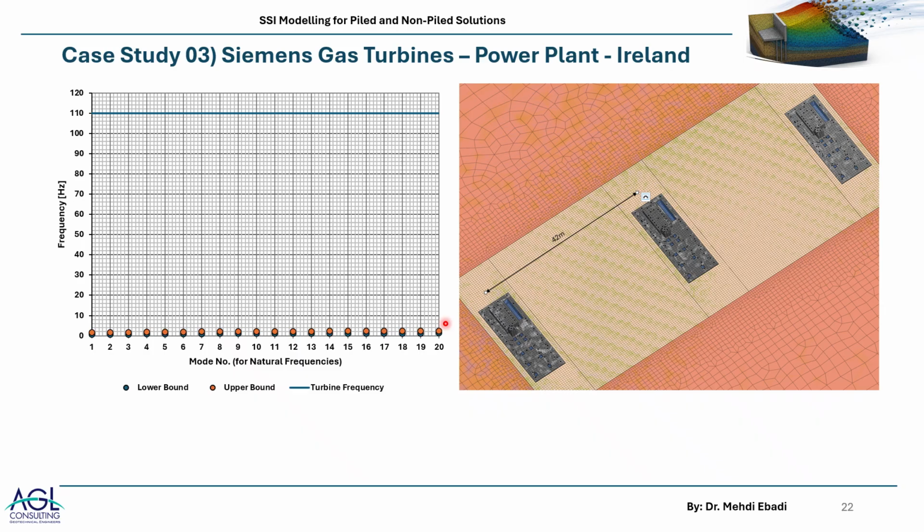Note that although for such a case we have the option in MIDAS to apply a sinusoidal load and do time history analysis, we didn't find such an analysis useful for the needs of the project, because when you know that the settlements are well within the capacity, your system is not at risk of resonance or such, then doing time history analysis is not something that would add much to your findings from this project.